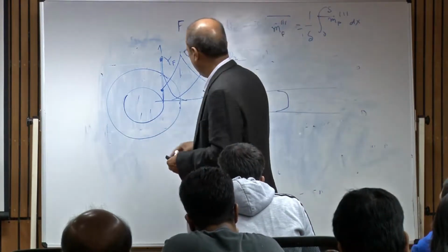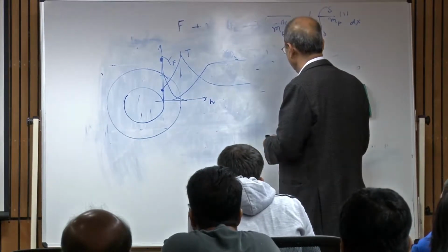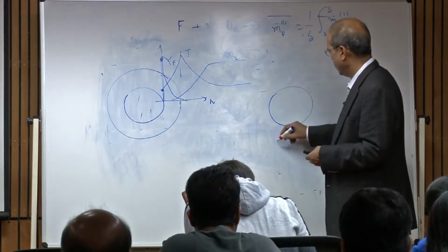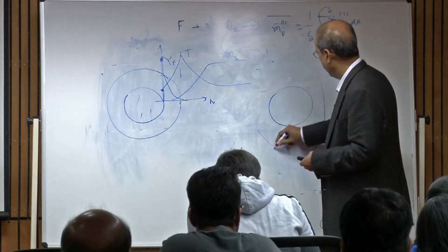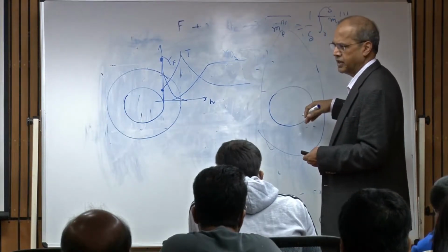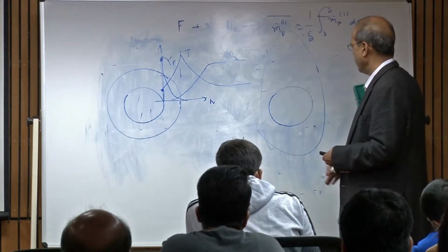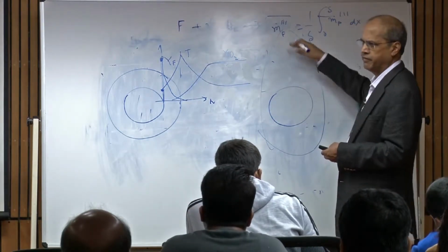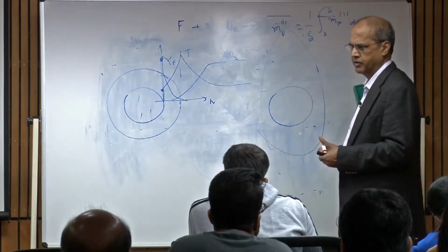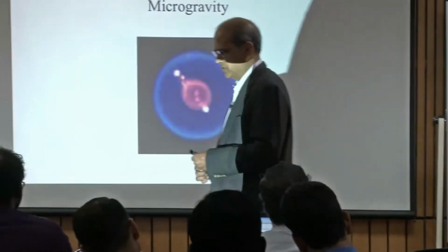Now, I was saying the flame is spherical under microgravity condition. If you have gravity effect on this droplet, the flame will have this shape because of buoyancy. The light gases, the product species, have a buoyancy effect, so there is a buoyant convection that will make the flame this shape. So it is 2-dimensional or 3-dimensional, and then the analysis also becomes more complicated.